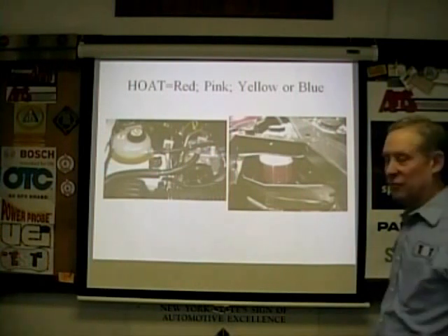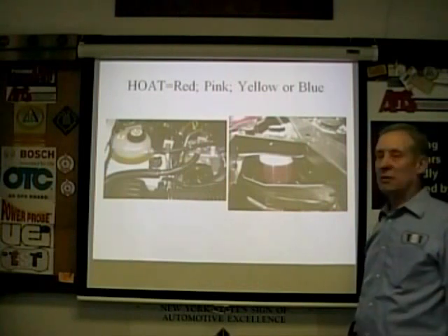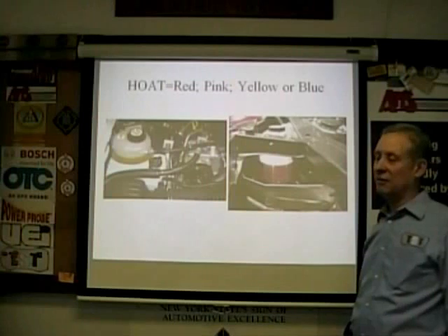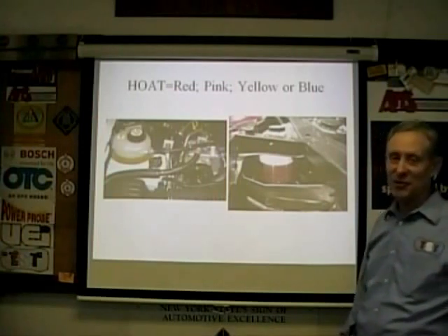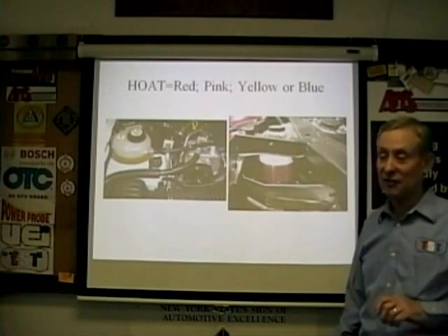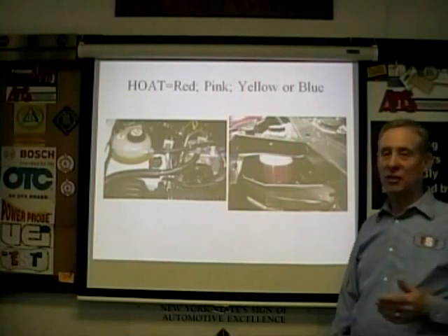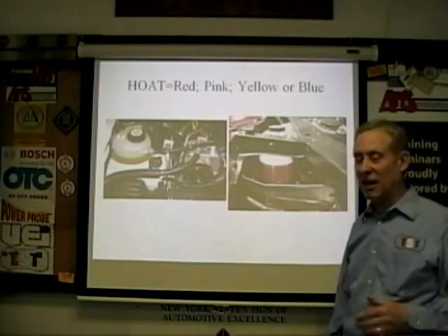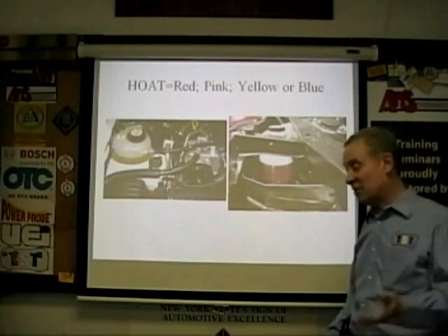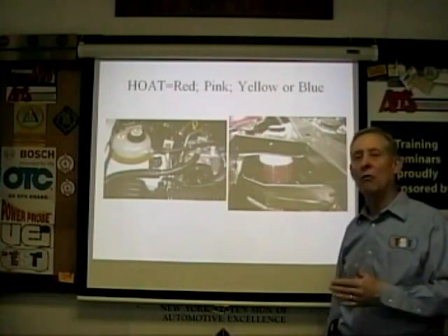And how about the guys that put additive color in when they're reusing the antifreeze by cleaning it up and recycling? That's the other issue, and that's part of why I say if you don't know what's in there, I'm going to say it again. If you don't know what's in there, you have to flush it out and make sure the right stuff is in there, because there are shops who are selling remanufactured coolant. They have a machine that cleans it out, strips all the dye out, supposedly neutralizes, sets it to the right pH, puts an additive package back in, and then puts a dye in. Do you really know that that's right?